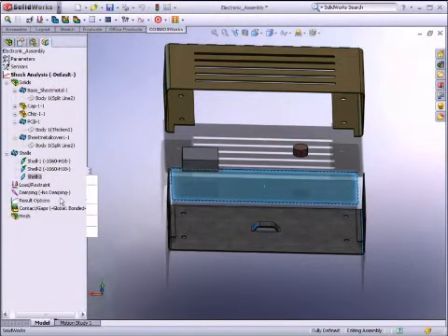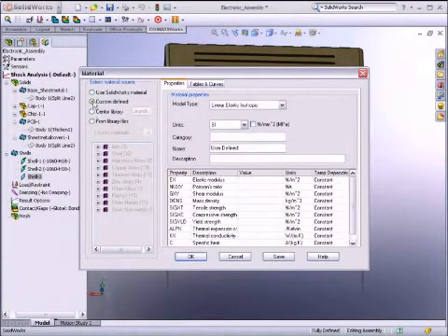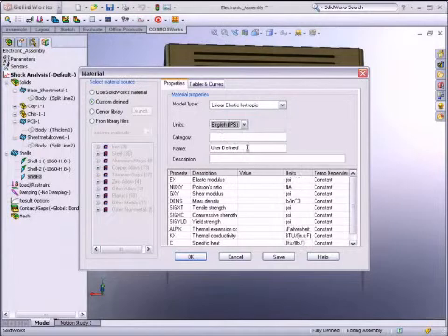If you do not have a certain material in your library, you can create custom materials on the fly. As we continue to set the materials, notice the combination of solid geometry and shell geometry in our analysis. SolidWorks simulation gives you the tools to choose the most efficient mesh for any given problem.